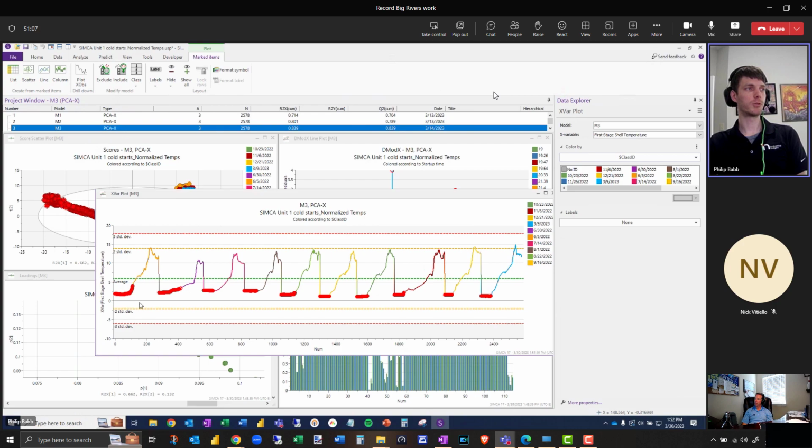This is the turbine metal temperature. So that's the goal when they're starting up, is to heat up the turbine, right? Each one of these humps is one of the startups. And this first section, you can see highlighted, this first part of each startup, is before that temperature starts to increase, which tells us that this is when they're getting their boiler ready to release steam to the turbine to actually heat the turbine up.